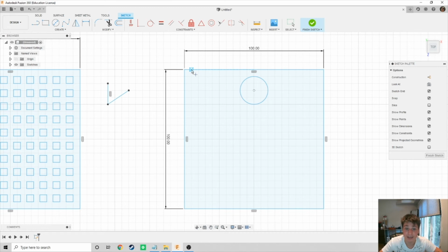When I'm at the intersection of one of my grid lines as well as on my face, I'm going to get a box with an X. When I'm on the corner, on the vertex of my shape, all I'm going to have is just a normal square. Now notice when I get to the center of my square, I'm going to have my point, my X, as well as this triangle. Anytime you're working with, whether that be on paper or in CAD, a triangle denotes the midpoint. This allows you to reference the midpoint and know that this is an axis of symmetry right here.